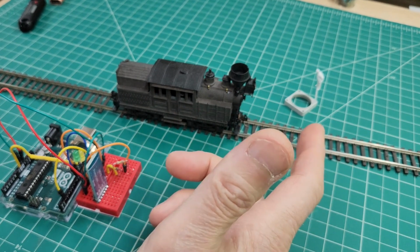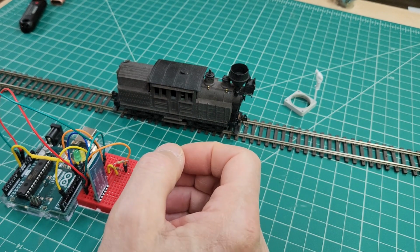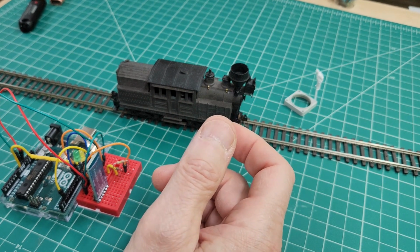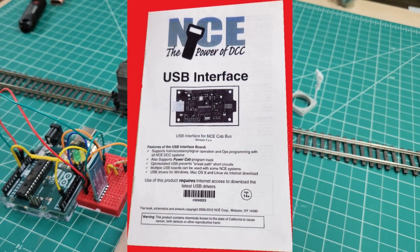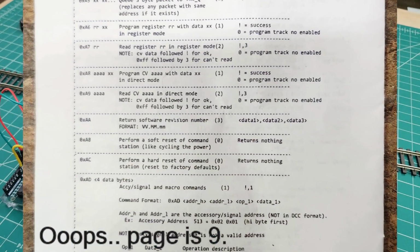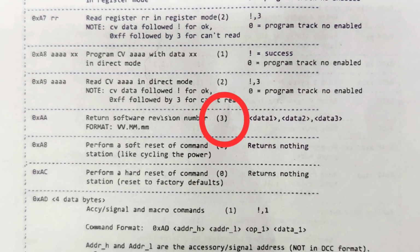So the Arduino code initially received a single byte from JMRI of AA hex. Fortunately, the NCE USB interface ships with documentation. This is what I'm showing. On this page, page 5, the AA is described as a request for the software revision number, and that it requires a 3-byte response.